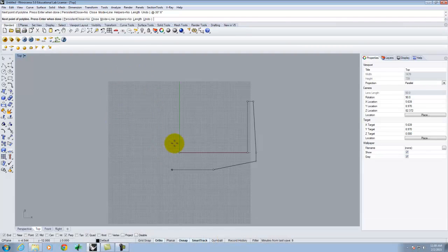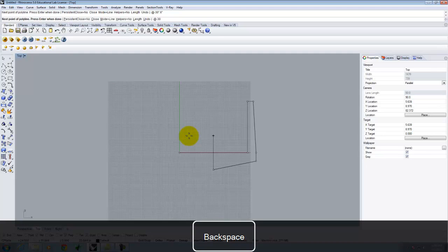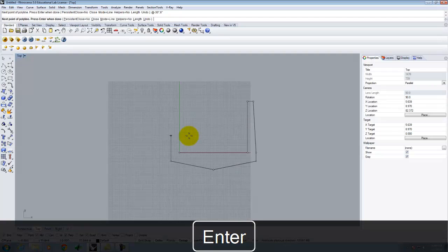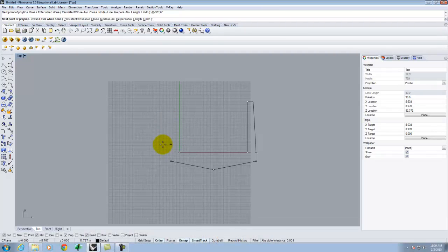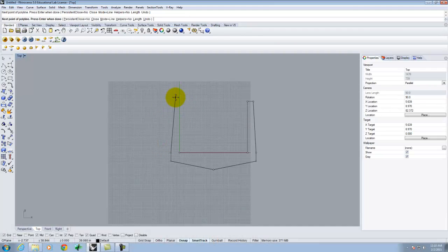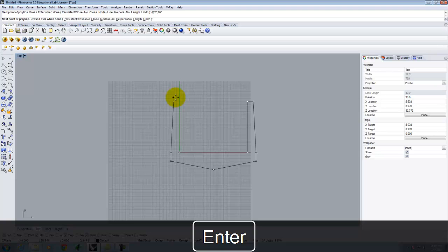Whoops, I didn't have a comma, sorry. At negative 30 inches, comma, not period, 6 inches. That gets me back up. And so I'm going to go up 6 inches here. And then I need to go, again, relative coordinate, at 2 inches, comma, 36 inches, to create that part of